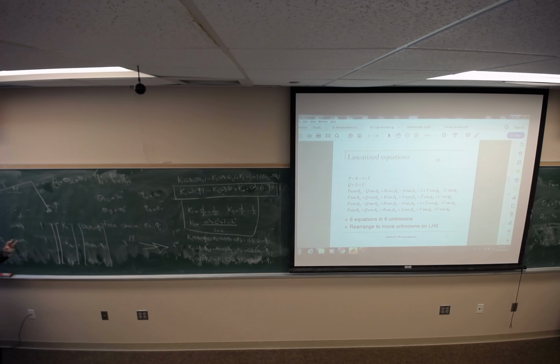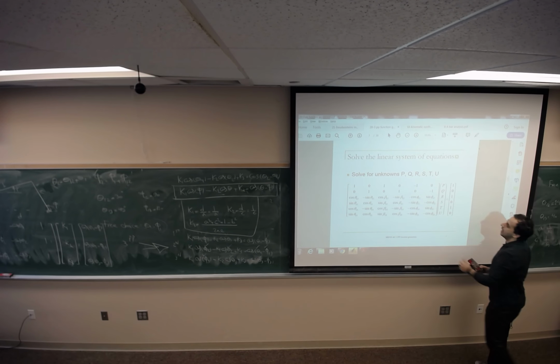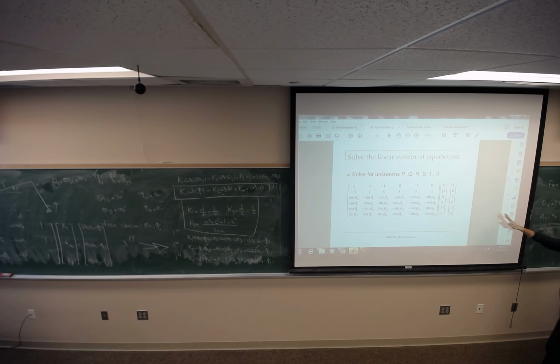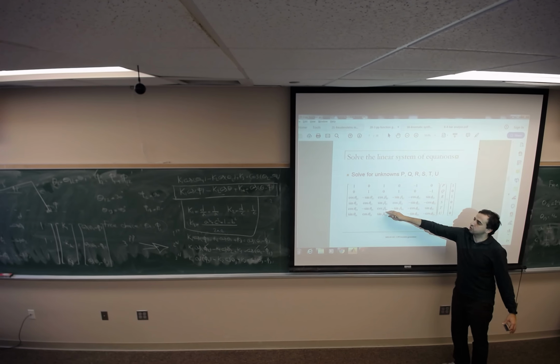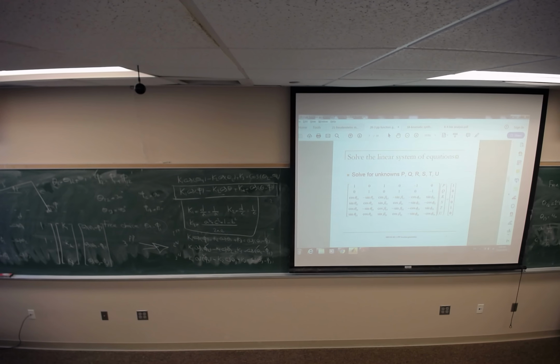Those problems, both problems, are solving for A, B, C, and the input angles. But in the previous method you need the free choices beta 12 and beta 13. In the Freudenstein method, the free choices are theta 1 and phi1.